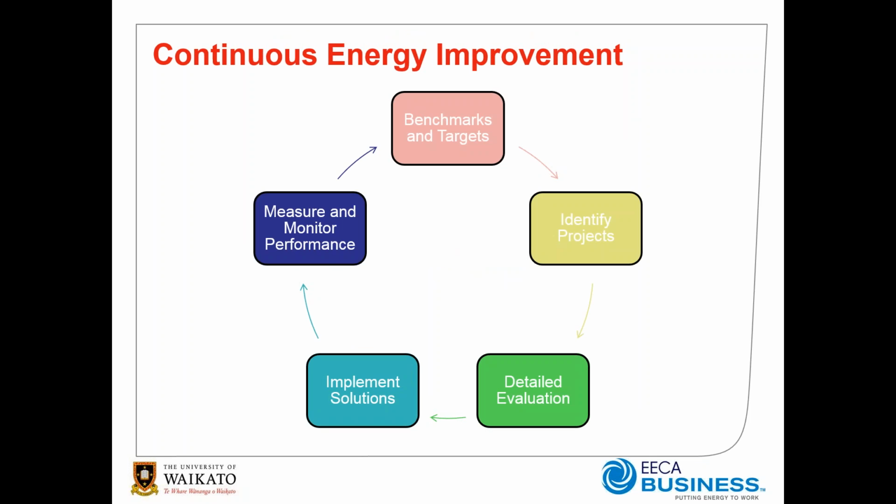This targeting and benchmarks is to essentially quantify your energy performance, compare it against perhaps what is the best technology available or the best that your particular technology is able to achieve. It's to set specific process targets and to apply some of these tools that we have in order to do that, such as pinch analysis, which is today's focus, or process simulation.